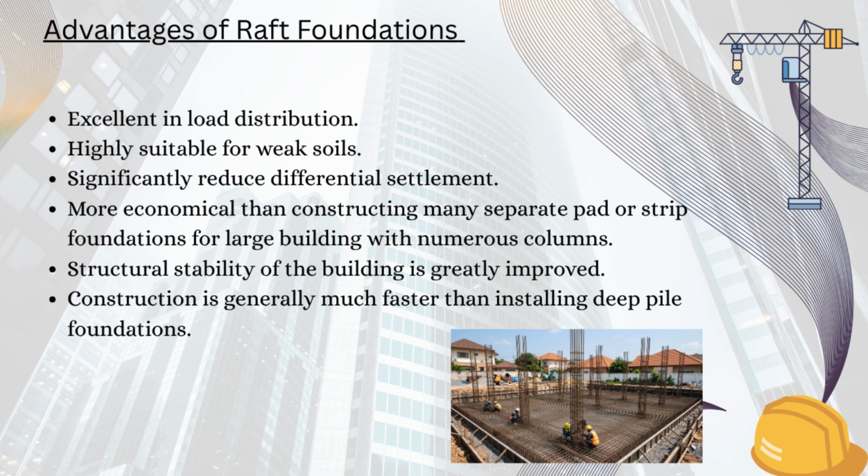The biggest advantage is its excellent load distribution. Since the entire building rests on one continuous slab, structural loads are spread evenly over a very large area, greatly reducing soil pressure. Raft foundations are also highly suitable for weak soils, where isolated footings would experience excessive settlement. They significantly reduce differential settlement, helping the building settle more uniformly and reducing the likelihood of structural cracks.